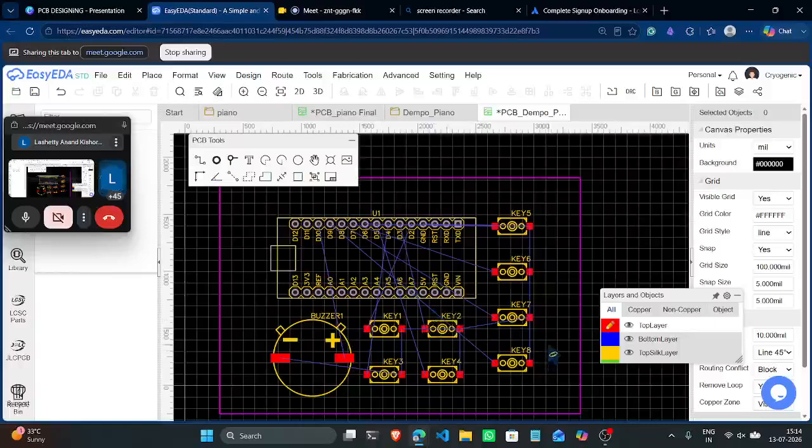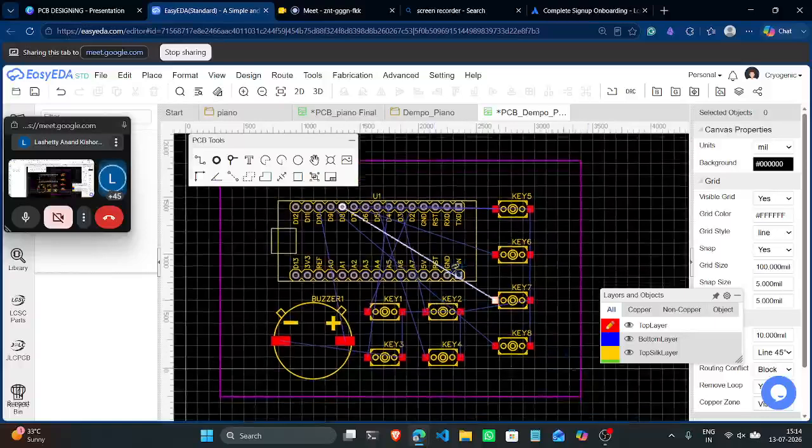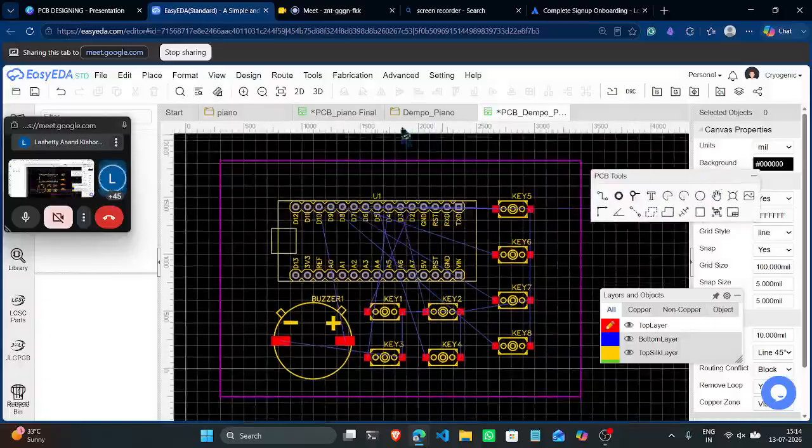So to ensure that won't happen, engineers designed a structured way of designing a PCB. They create the schematic first, then import it to PCB layout so that you get these blue lines, and you call these blue lines rat lines. We call them rat lines in an engineering context. So this will show you the connections you need to make, and you can just focus on routing.